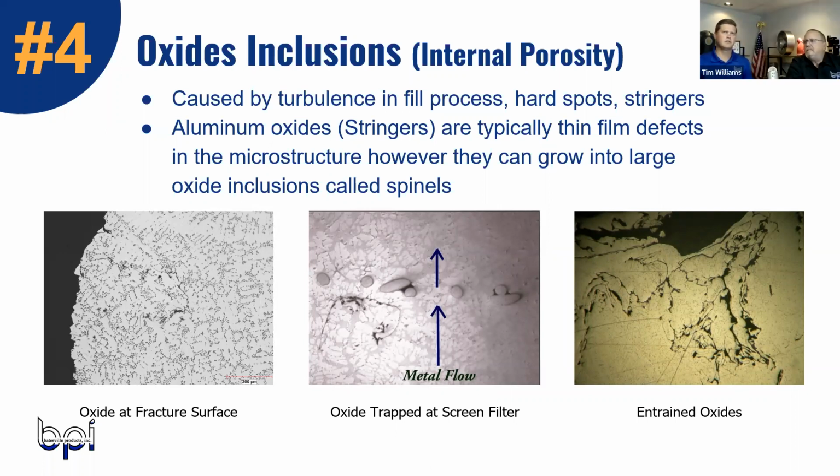Monty, something like this, like the oxide inclusions, you were stating typically this isn't anything you would see in permanent mold, and is that because of the gradual tilt pour that really solves this out of it? The time it takes, and also you don't get the turbulence normally like you do dumping down a sprue, or even oxygen also has a little bit to play in it as well. Okay. So is it something you can see in die casting? I'm ready to say that, yes. Okay. You can, yeah. But is it most common then in a sand casting atmosphere?